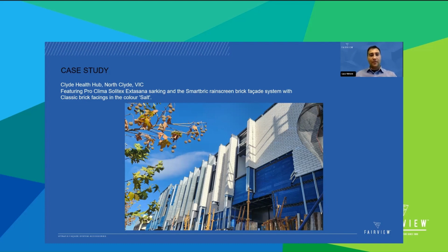The first question is about precast walls and how moisture is prevented, since this is a closed facade system. Usually, when you have a precast wall, your moisture is actually coming from inside. The best your precast wall can do to stop water ingress is a sealed outer skin. But you still possibly have some moisture depending on what is behind your precast wall. So either a vapor control layer membrane will be required, or you allow the vapor to travel to the second layer of the wall buildup and get removed by the cavity.